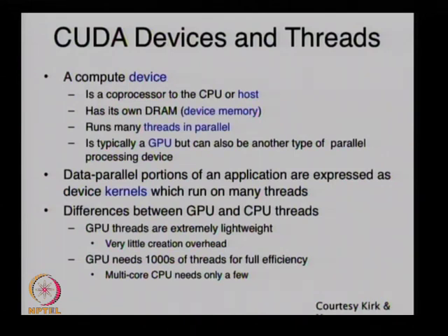Okay. There is a separate memory which the GPU has. It cannot get data directly from the system memory, which probably will change over time, but right now it cannot, which means every piece of data needs to be transferred, copied by you into the GPU memory before the function will start.